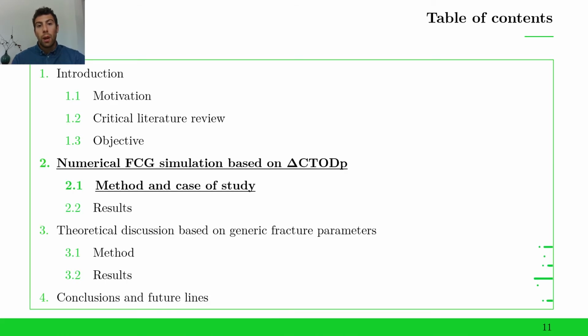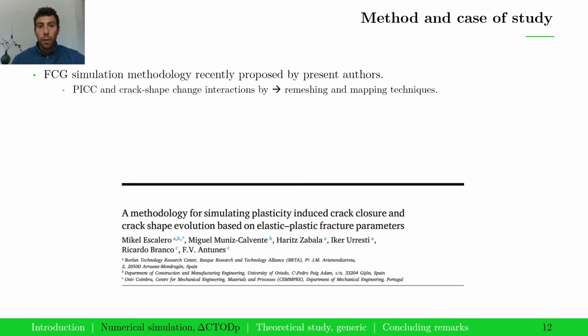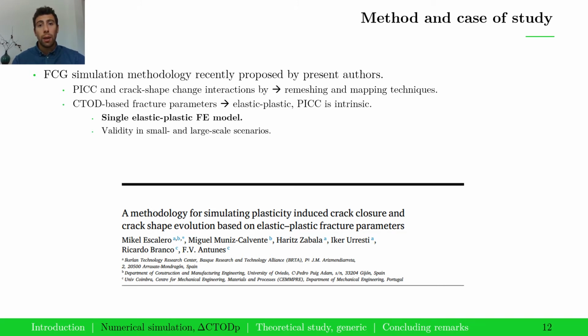So let's address our fatigue crack growth simulations. In this work, we simulate fatigue crack growth with a methodology recently proposed by the authors. This methodology considers the interaction between plasticity-induced crack closure and crack shape evolution through remeshing and mapping. And the main novelty has been the use of crack tip opening displacement-based fracture parameters.